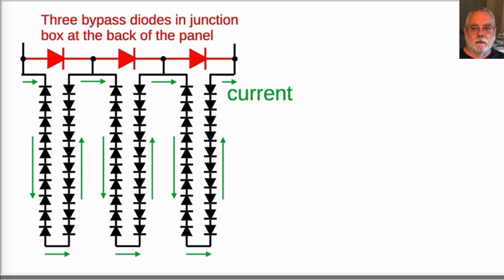When all solar cells are fully illuminated, or all solar cells are illuminated equally, the voltage sourced by the solar cell strings is such that the three bypass diodes are in reverse bias, off, and do nothing. The bypass diodes are not solar cells. The bypass diode's reverse saturation currents are insignificant compared to the solar cell's currents. They don't reduce the solar output.